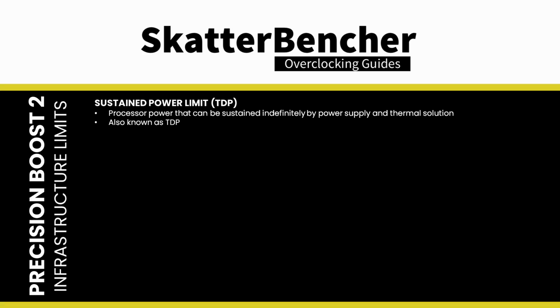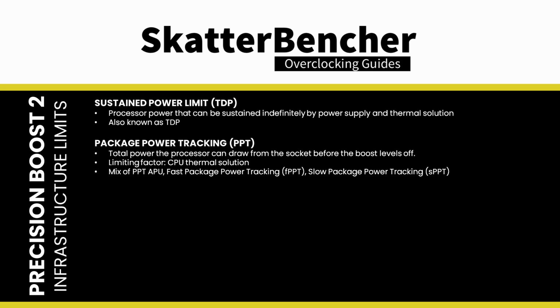Sustained power limit, or SPL, is the processor power that can be sustained indefinitely by the power supply and thermal solution. It is also known as the TDP. Package power tracking, or PPT, is the total power the processor can draw from the socket before the boost levels off. Typically, the limiting factor is your CPU thermal solution.